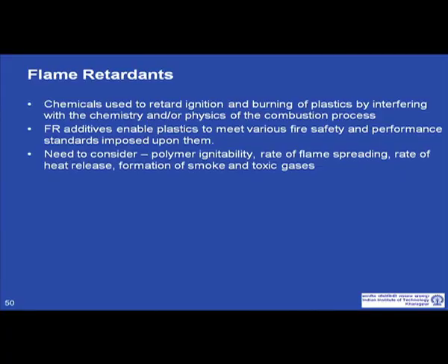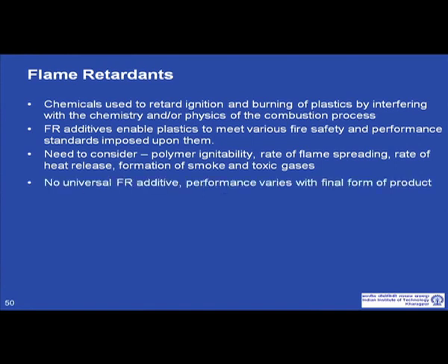Now, to design fire retardant additives, we need to consider the polymer ignitability, the rate of flame spreading, the rate of heat release, and the formation of smoke and toxic gases, as we mentioned before. One thing one must note is that there is no uniform FR additive. It is not that one FR additive is best for all polymers.